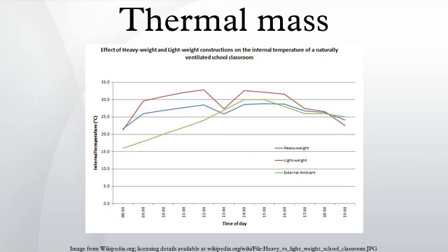When temperatures fall at night, the walls re-radiate the thermal energy back into the night sky. In this application it is important for such walls to be massive to prevent heat transfer into the interior. Hot humid climates. The use of thermal mass is the most challenging in this environment where night temperatures remain elevated.